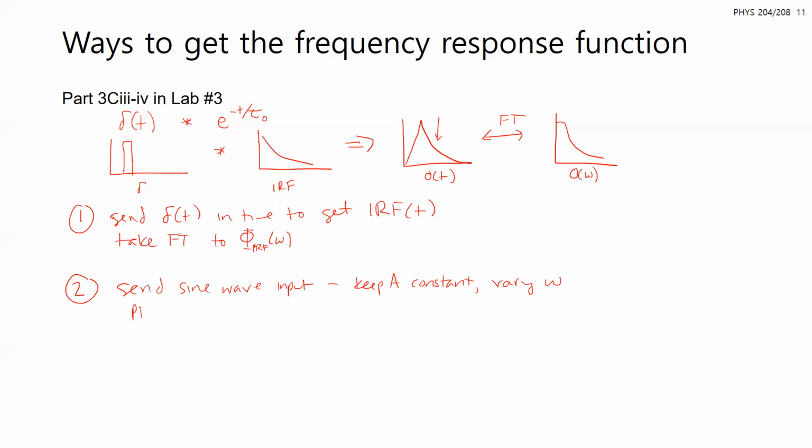And then if you plot the change in your amplitude for the output versus the frequency you're sending in, you can then get your frequency response function.